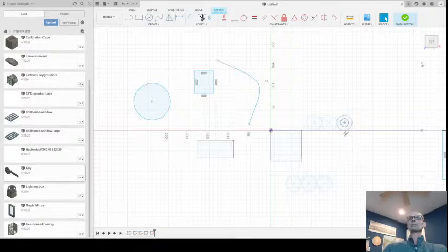So you notice over here in the sketch palette, which will pop up when we're in sketch mode, you'll see two things. When you go into sketch mode, you have to start and end the sketch mode. And to end the sketch mode, once you're in it, you'll see a big green finish sketch button over here in the upper right-hand corner, or this finish sketch button here that's part of the sketch palette pop out. And so at the top of this list is something called construction.